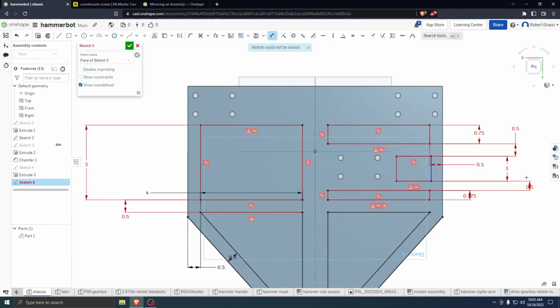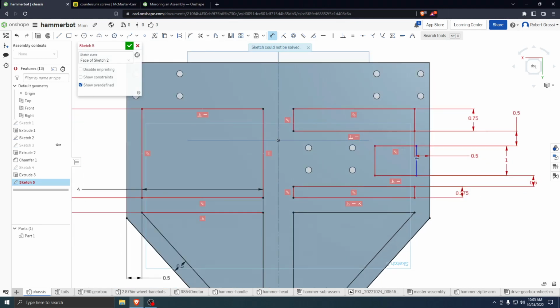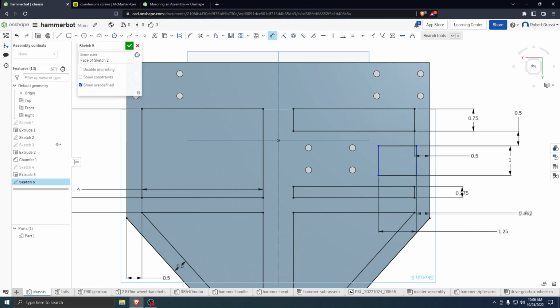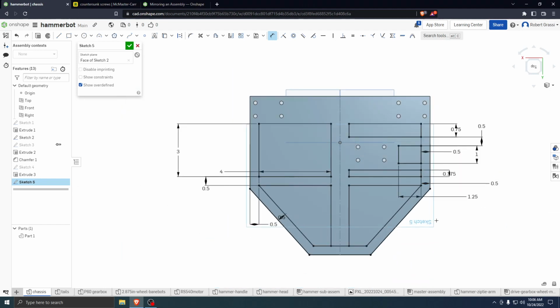Oh, okay. See what I tried to do there? I tried to over-define the sketch, and it throws an error because this is already a dimension that is known. So I tried to dimension something I should not have, and it will flash red and scream at you. So good, and distance here we really want this to be 0.5. So yeah, these dimensions add up pretty quick, huh?